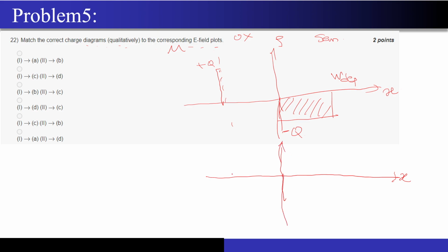So now what I told you over here, the charge density that you are seeing over here, there is actually no width present. This delta W is actually zero, because metal has so many free states available that whatever charge density it wants to accommodate, it will just accommodate in an areal kind of sheet. It doesn't require any depth or width over here, right? So you can consider it like an impulse function.